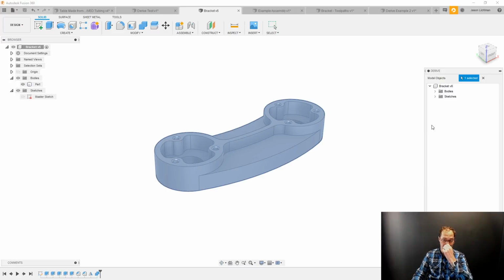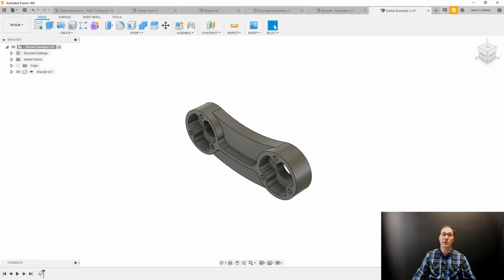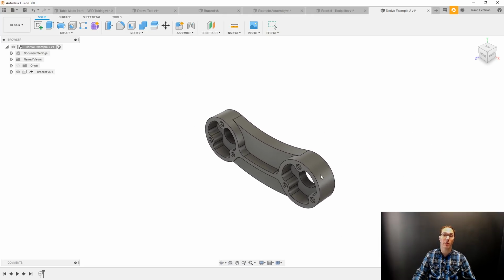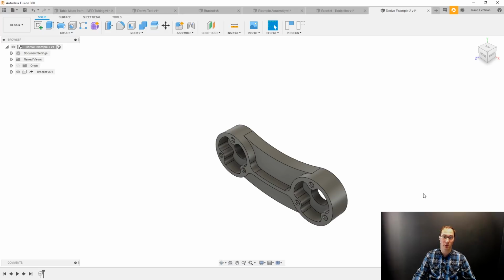And by the way, we do also have an option down here for bringing in parameters as well. So not everyone probably clicked on this drop-down arrow to see what parameters is going to mean, but you could bring in parameters if your design had parameters, and I'll bring it in too. I like using the root level because when I say OK, it's going to not only bring in everything, but now I could move this component and reorient it if I want to. And that to me is really, really helpful.